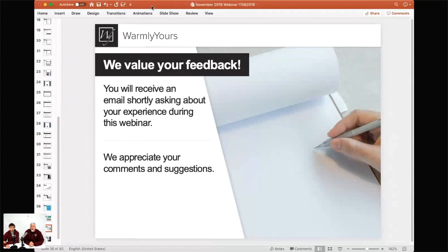Luxury vinyl tile, we have a video online. You go to WarmlyYours.com and go into Learn and then click videos. And there is an installation that we did with LVT that shows you exactly how to do it. It's done with a temp zone product covered with 3/8 to 1/2 inch of self-leveling cement. And then you have a nice flat floor to put the luxury vinyl tile on. So very good question. You're welcome. Thank you. You got in just in the nick of time, and it's a question we get every single day. So I'm glad you asked it.